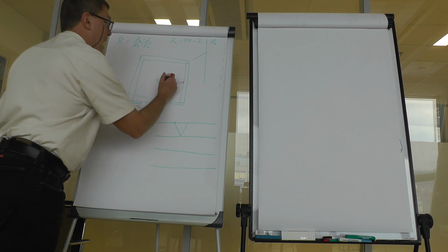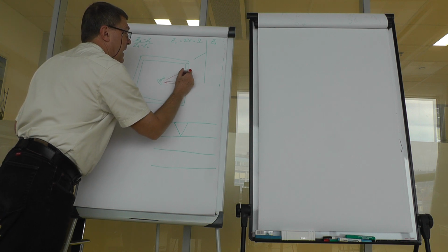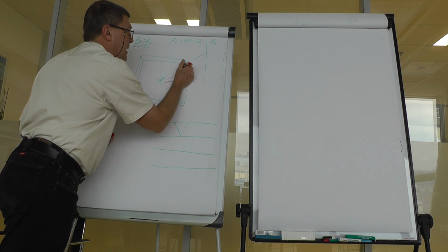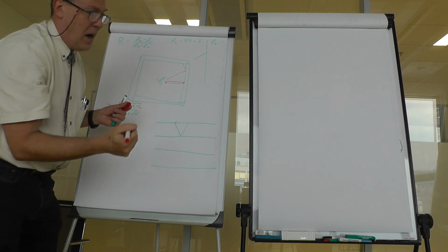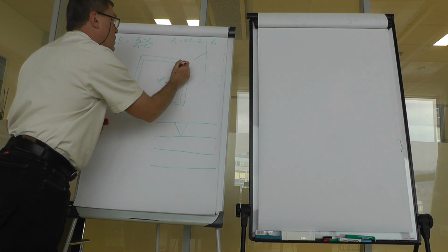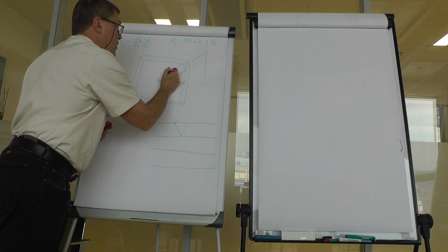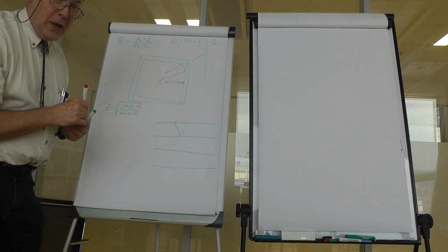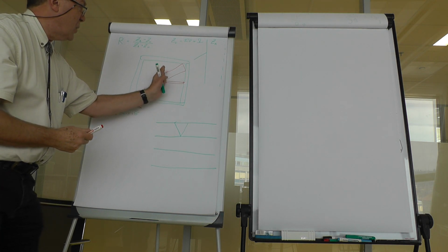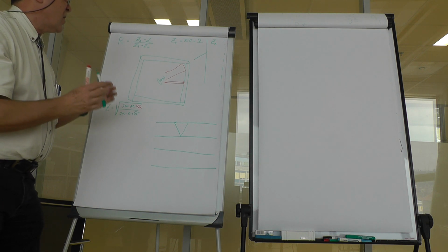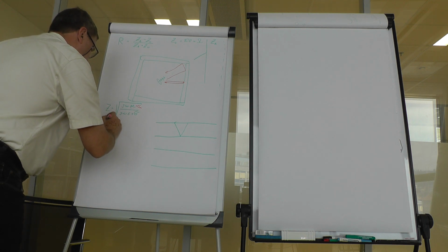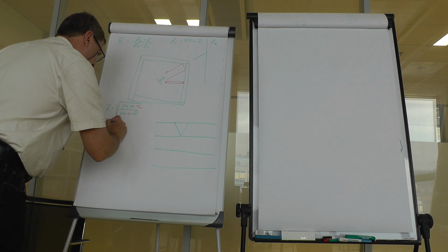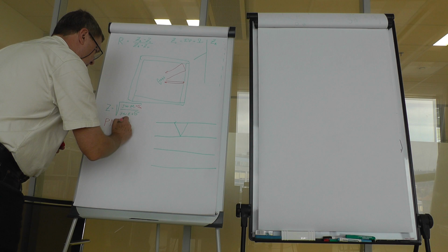Now, if you have a wave that makes it under quite different angle, then you have several reflections which are not zero but small, so then you get sufficient damping before the energy returns to the area of interest. So this is the first concept, which is mostly named like perfectly matched layer.